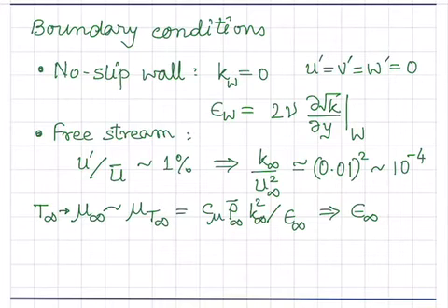So this can be computed and we can get a value. Now, how reliable are these values? This is just an approximation. It turns out that if you're computing a turbulent boundary layer on a flat plate or any geometry, the results that you get in a turbulent boundary layer are not very sensitive to these values as long as they are non-zero.